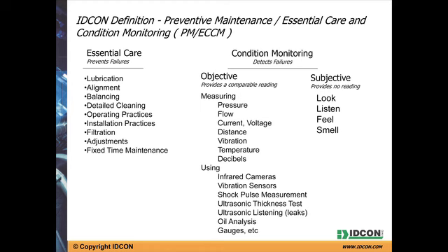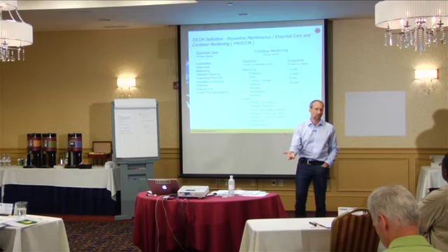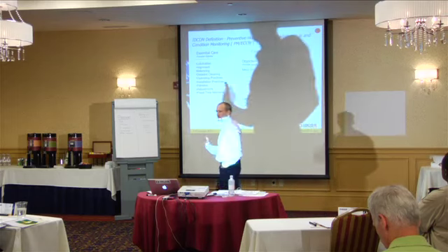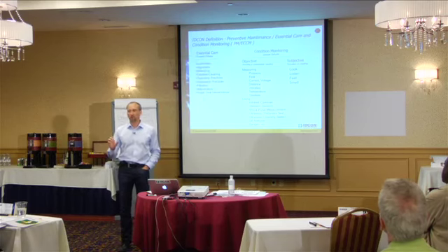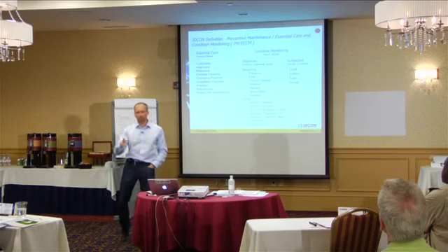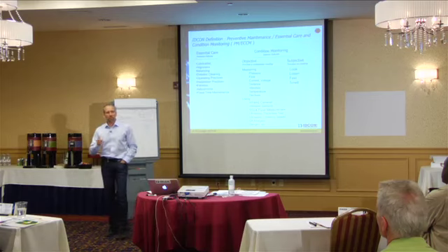So if we have a temperature check that we do with putting our hand on the motor, both for safety reasons and of course information, if we can take that temperature on the motor with an infrared temperature gun, that's much better. Now whether we record that temperature or not, that's a judgment call. Some people say we're going to record everything because we need to check that people are actually doing this. I'll buy that if you actually do that.